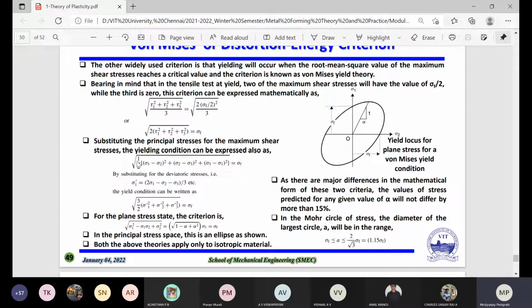But now, if you want to solve from this equation to this equation, you have to open this bracket. For example, this is a minus b whole square, so you have to write a square plus b square minus 2ab. And if you put it into this equation, you will find sigma 1 dash equal to 2 sigma 1 minus sigma 2 minus sigma 3 divided by 3 from this equation. I'll just put it directly here, so you can try it at home.